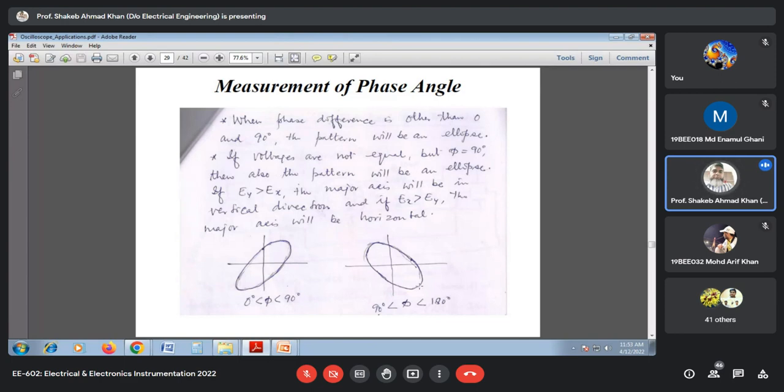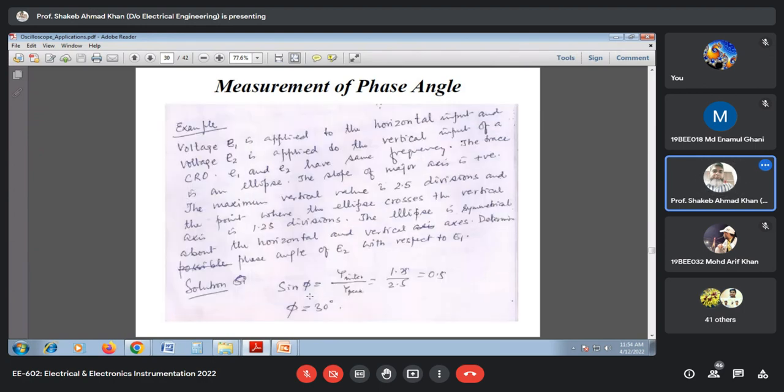second and fourth quadrant. Then the phase difference between the two voltage waveforms will be between 0 and 90 degrees when you are having first and third, and between 90 and 180 degrees when you are having second and fourth. Obviously, when two waveforms are out of phase, the maximum is 180 degrees, and the minimum is 0 degrees. So this is the way we can find it, and this is the rule.